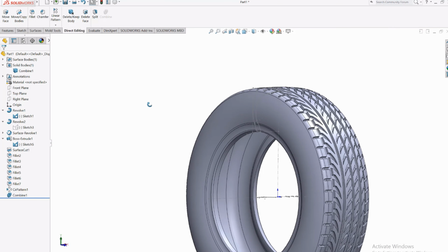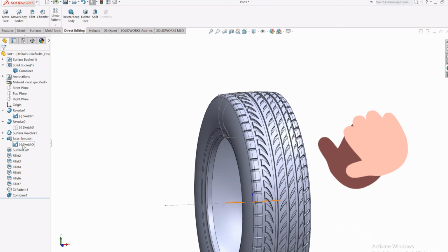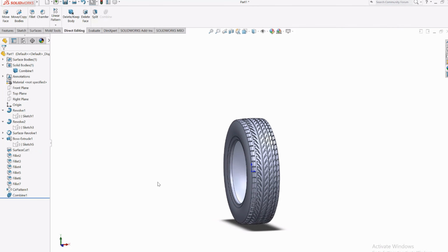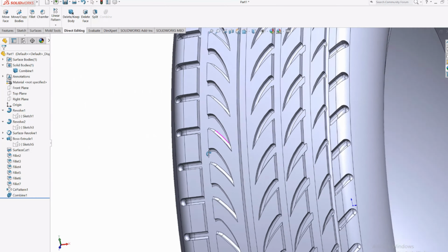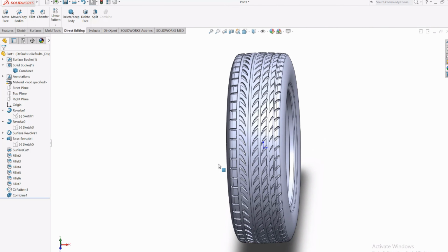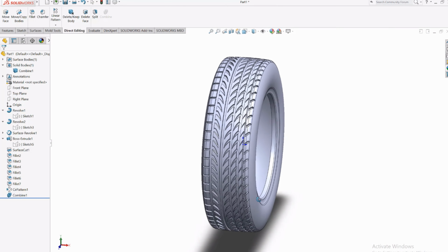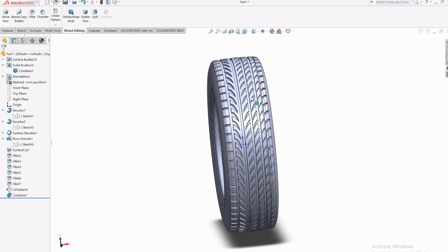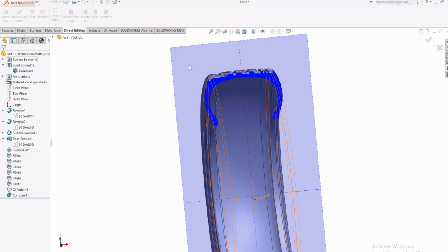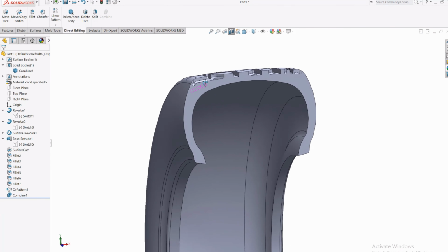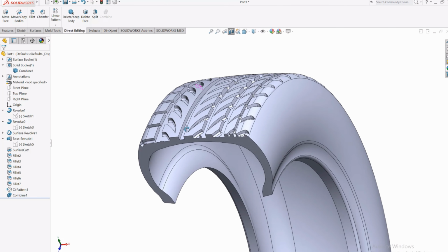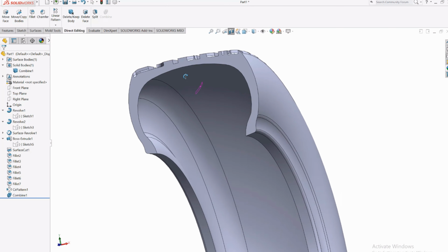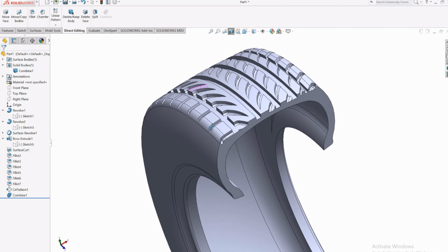So now, our tire design is completely ready. You can see our tire here has 4 big grooves and 1 small groove. Apart from that we made sipes, shoulder cutouts and tread blocks too. We can see the cut section of the tire thickness also. Tyre designing is very important process and hence the time required to do so is more as well. You guys can follow the process followed in this video for easy understanding and designing.